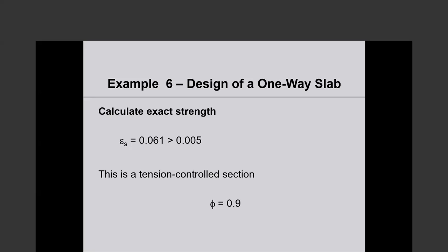So my question is, when you say beam's capacity was checked, why didn't you include the slab in the first place? That's part of the beam. Why would you even check without the slab, without the overhanging flanges?